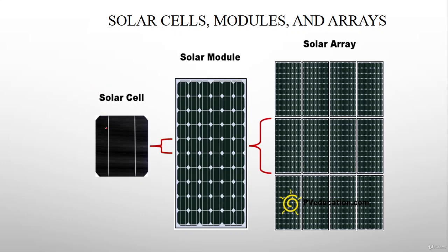So we know the solar cell is made up of a polycrystalline type of structure or a monocrystalline type of structure. The number of solar cells we are connecting row-wise in series combination, by joining the bus bar intersections with each other, gives us some amount of voltage, let's say 30 volt, 37 volt, and the current is approximately greater than 8 ampere.